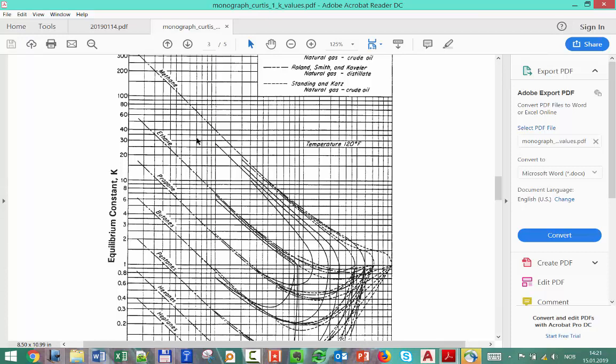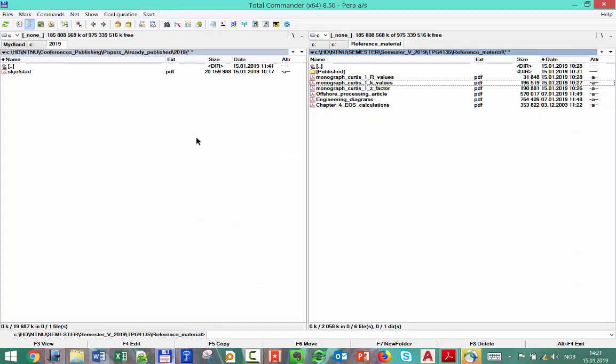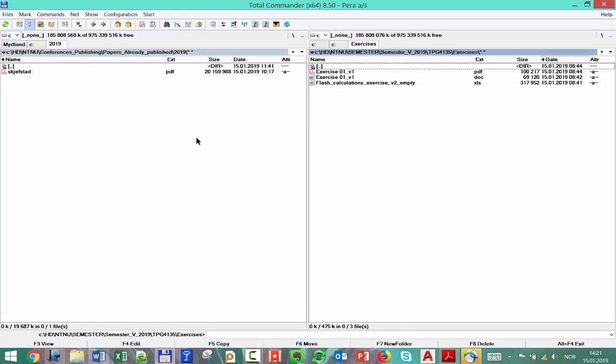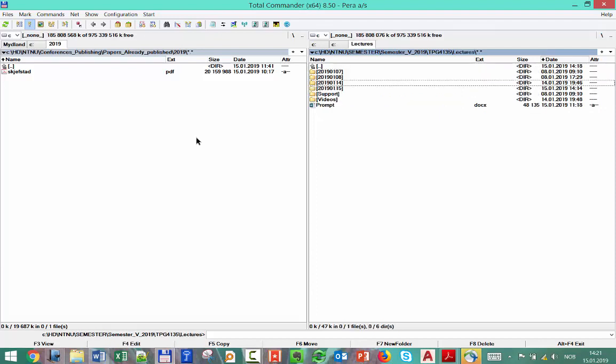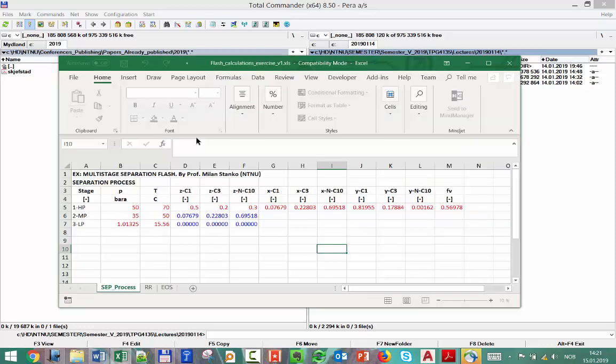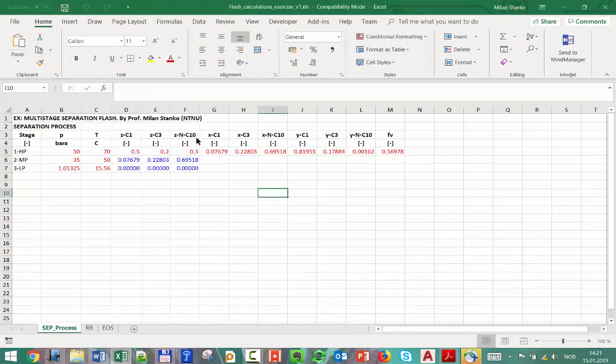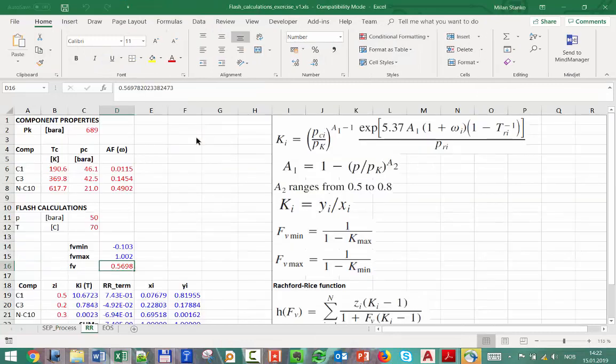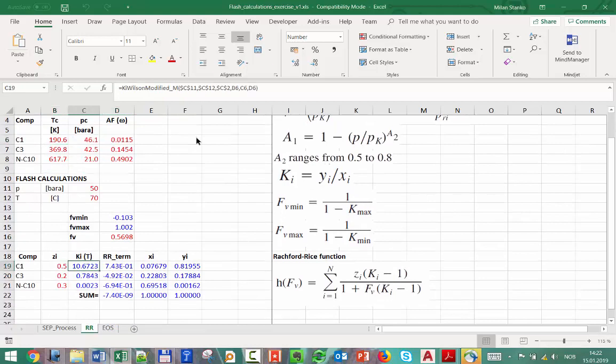And that dependence, in our case, if we remember the exercise we have done, how did we input that dependence? With 3 parameters. What were those? Critical pressure, critical temperature, and eccentric factor. So that's how we give the dependence; these 3 were an input for this Ki.